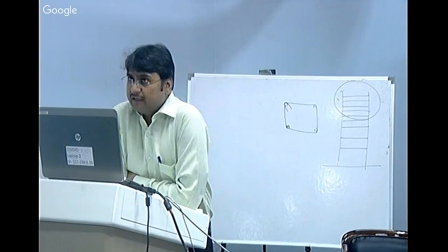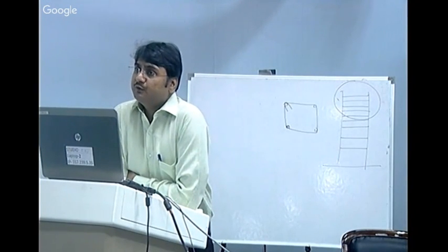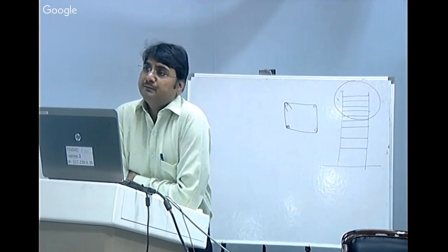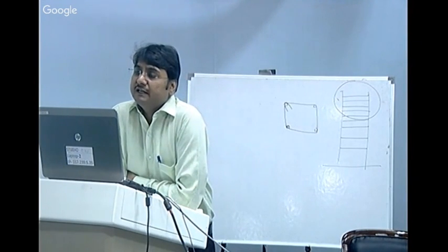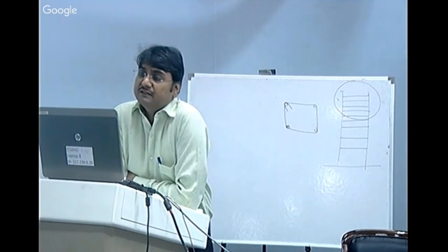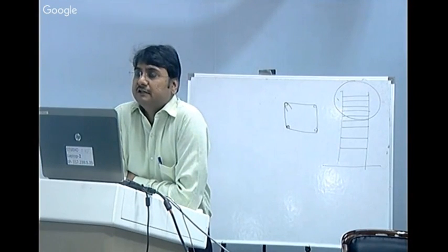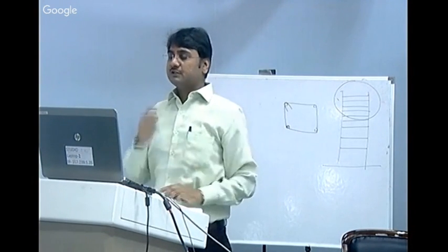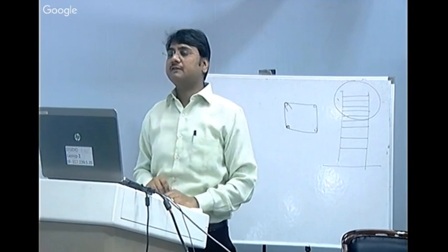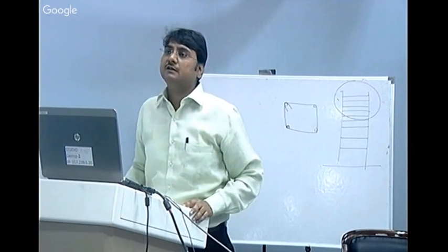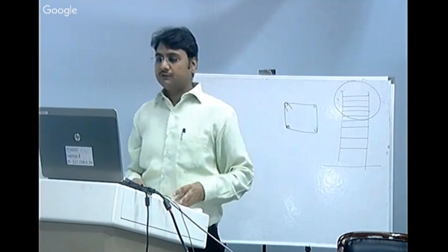Weak link, ductile behavior. I have improved the behavior of the structures by improving the elastic behavior of the building. I designed my building in such a way that the building remains in elastic state. It will come back to its original position. After the test, we observed that after attaining 10 centimeters of deflection, it came back to its original position. Okay. Now, somebody was asking what the futuristic plans for earthquake resistant design are.